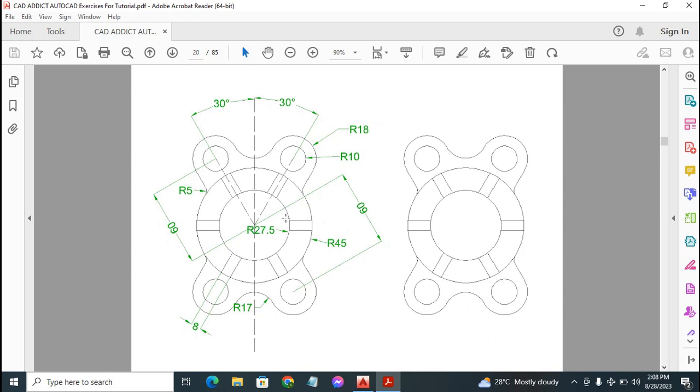Alright, so which means we need to get the center point of these smaller circles. We need to draw a larger circle with a construction line, of radius 60 millimeters. The point at which the circumference of this larger circle intercepts with the angular construction lines we produced initially, that point of intersection will be serving as the center of these smaller circles.